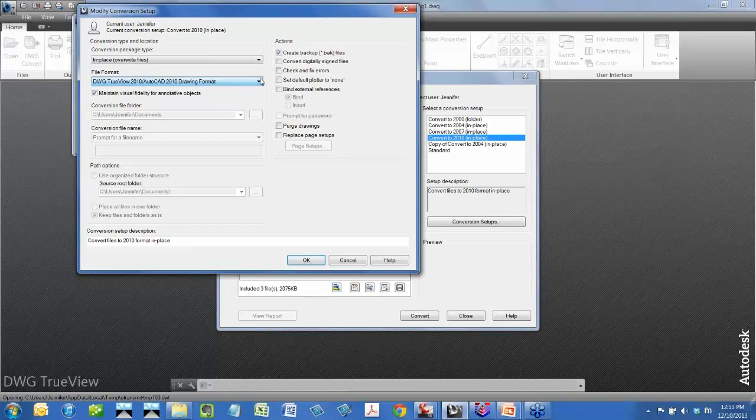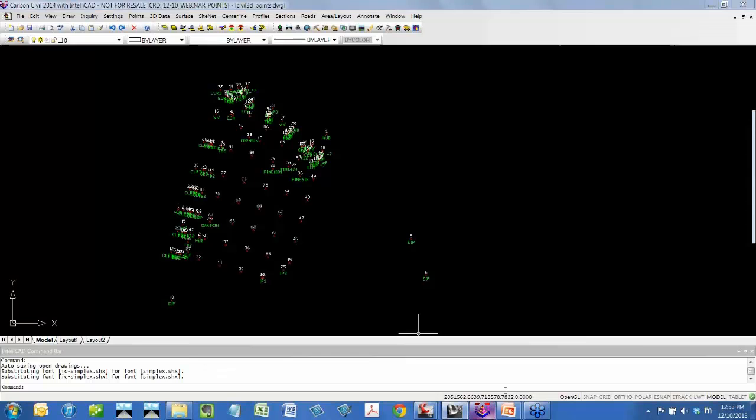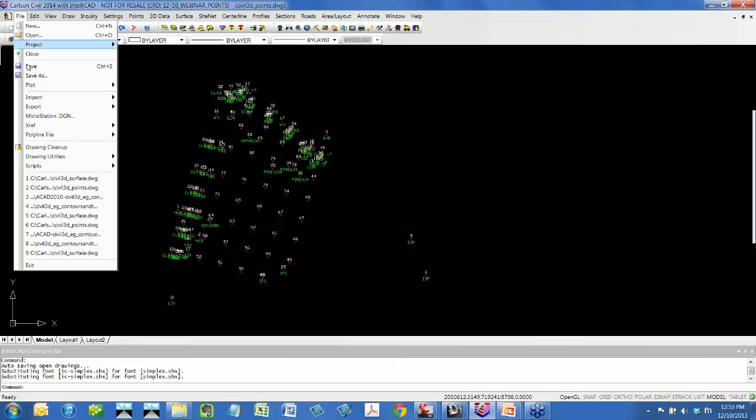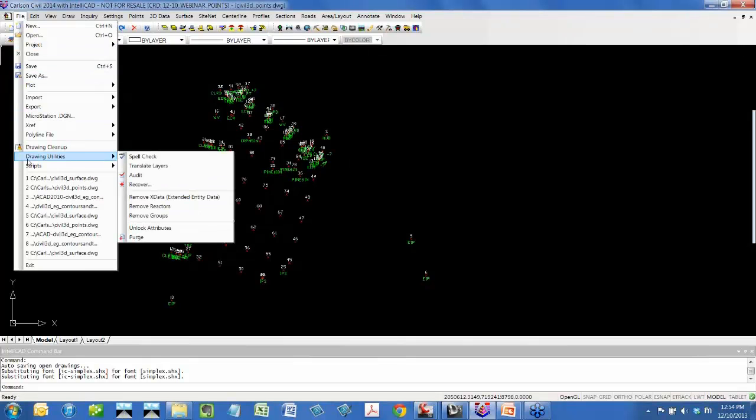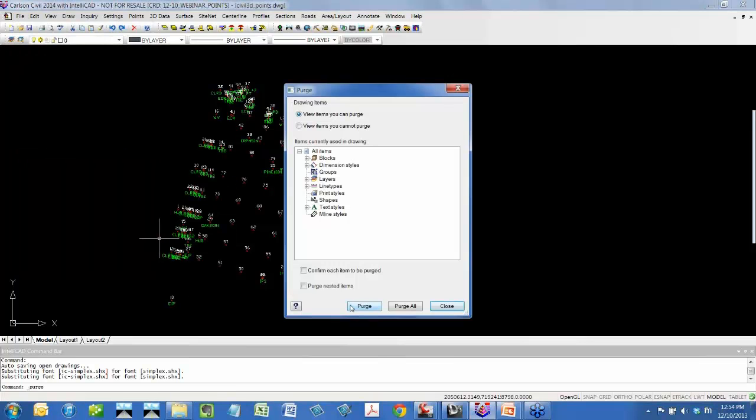Right. Yeah, someone just had a question. Do recover, audit, and purge work in AutoCAD? Yes, good question. Those are all in AutoCAD as well? Yep, so audit, recover, purge. And so it looks like I don't see that. And again, I think that's pretty new. What was it? Zero length line work and empty text entities. So it doesn't look like those are options, but it's very similar.